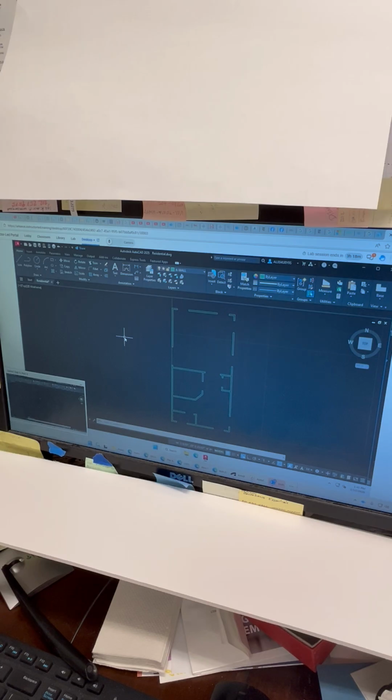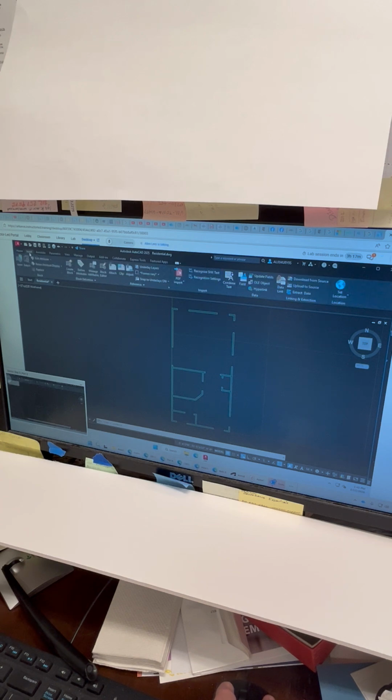All right, now you're going to see the benefit of this. Here's what I want everybody to do first. Everybody, change your current layer from a wall layer to the A-Glaze layer. That's going to be for windows. All right, next, I want you to go over now. This is the first time we're going to go to another tab officially. Well, we've been to the View tab, of course. But now, officially, I want you to go to the Insert tab. On the Insert tab, we have this Insert tool drop-down here.